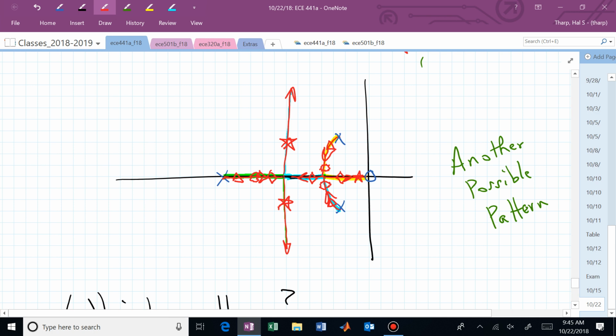And if I wanted closed loop poles at the clouds, I would pick k at that value, whatever I said that was, k equal 2. If I wanted my closed loop poles to be at the triangles, I would say, oh, k is 1/2. That's where I want my poles. Or if I wanted it to be where the stars are, then I might crank up k to 8, or whatever I said it was, 6 maybe. Is that clear? As I'm adjusting this knob k from 0 to infinity, the closed loop poles are moving according to those red lines on the complex S-plane.